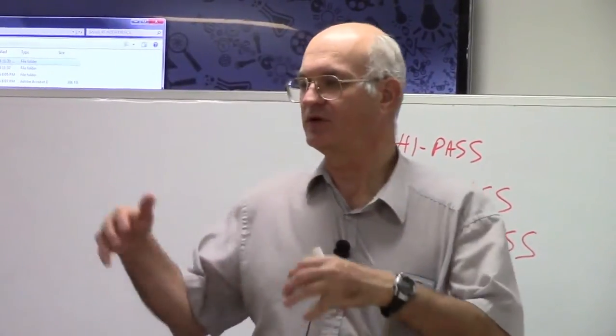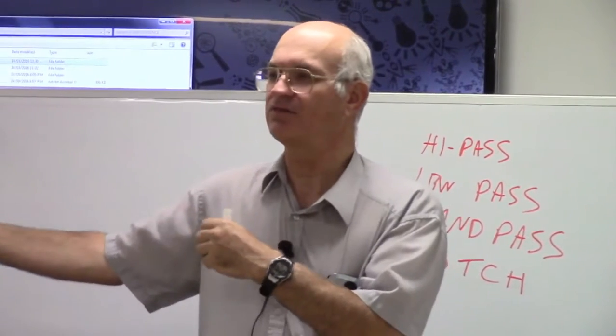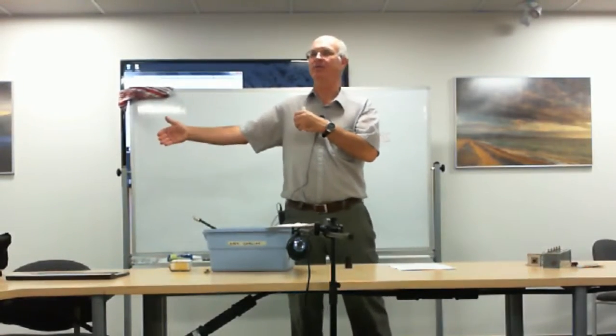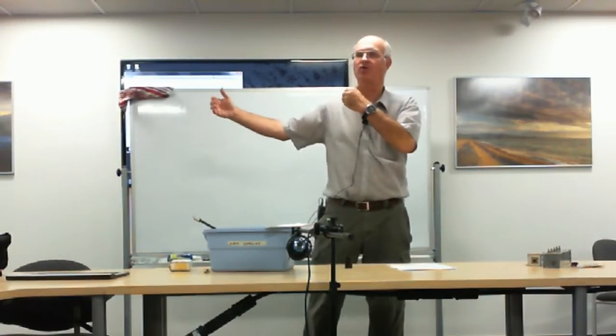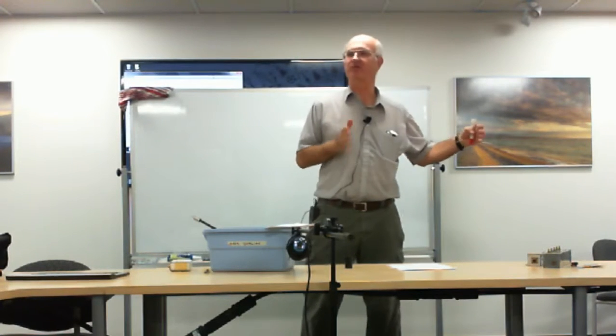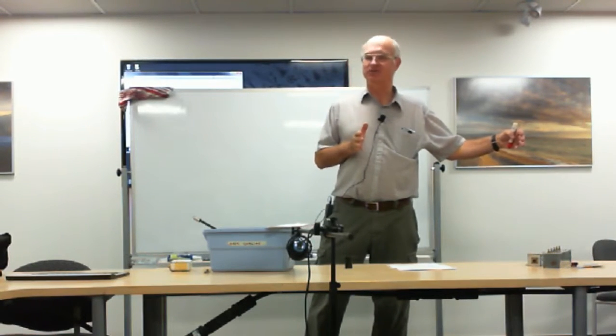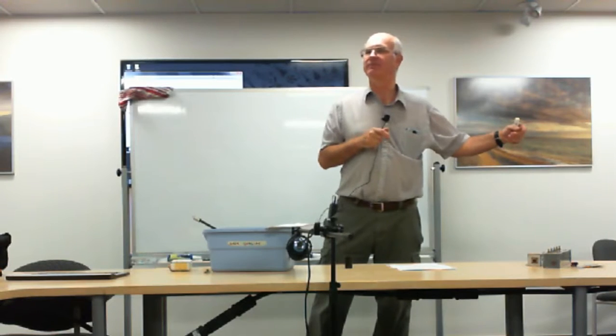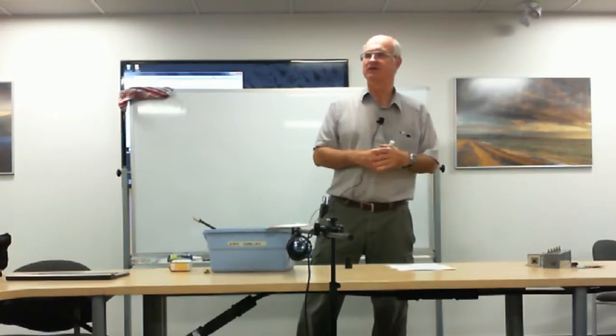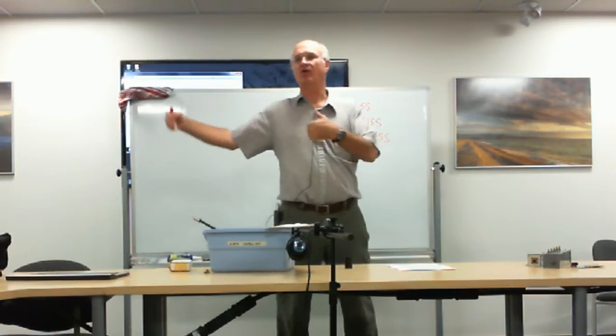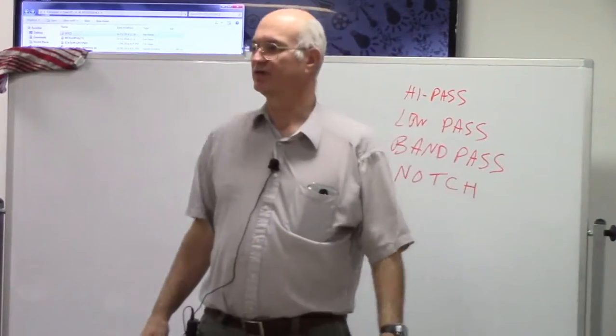So we don't care what's going on in the FM band, so we wipe out the whole FM band. We put in a bandpass filter that takes out the whole broadcast band, but doesn't affect the rest of the band. So now we know what we're seeing is real. It's not because of overload. So that's where you would use it when you wanted to get rid of a whole band of frequencies so that you could concentrate on something else.